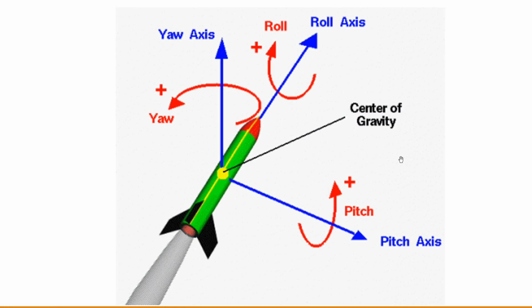Most rockets are designed to be symmetric along a line extending from the tip of the nose to the center of the nozzle exit. This line is called the roll axis, and rotation about it is known as rolling motion. Because the rocket is symmetric around this axis, this configuration is referred to as axisymmetric. Importantly, the center of gravity of the rocket lies along the roll axis.